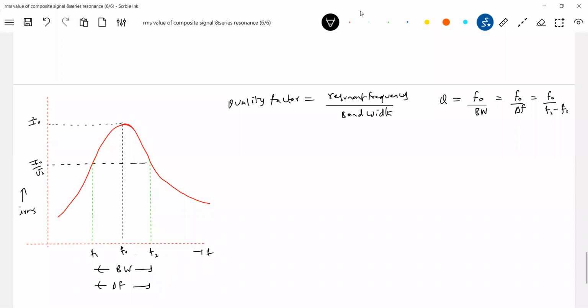If you go for the application, let's take FM, which I think you know now. Let's take 92 megahertz, which is the frequency of a station. Then the song, music, is the audio signal. How much frequency will all of that be? 20 kilohertz. So what should be the bandwidth of that particular station? The bandwidth of the station should be 20 kilohertz.